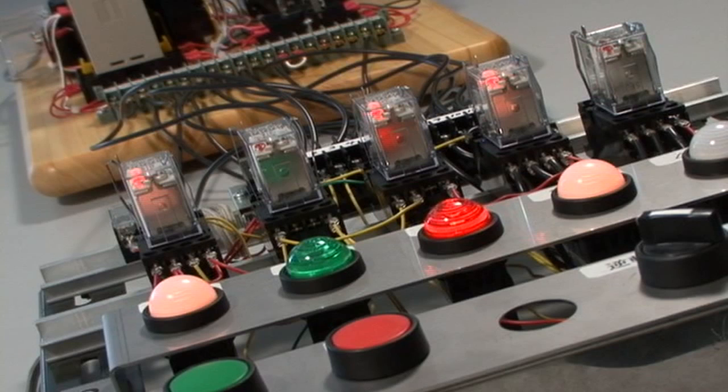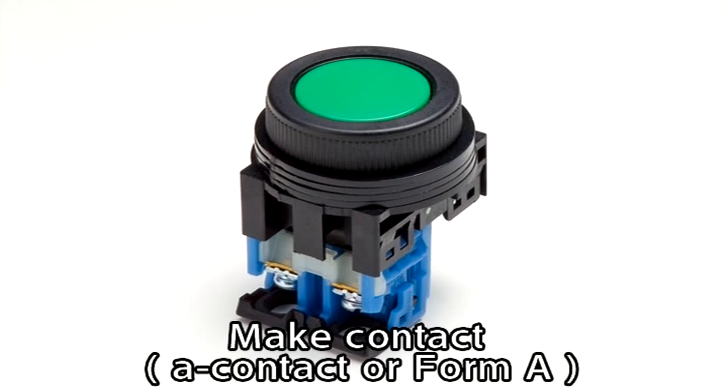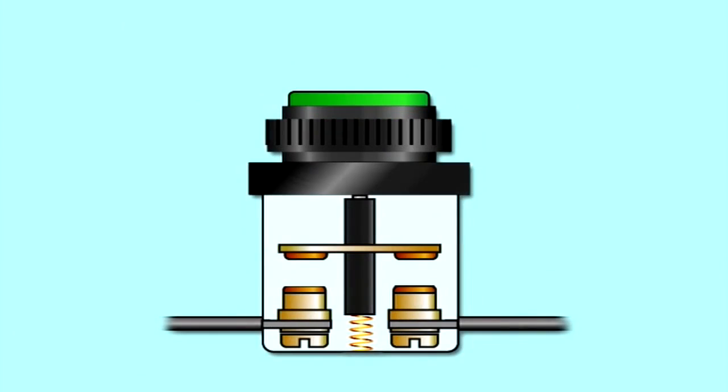Switches and relays are classified according to operation. The three types of operation are make contact, break contact, and changeover contact. Make contact is also known as Arbeit contact, which is abbreviated as A contact or Form A. If A contact is not in operation, the circuit remains open and the off state is maintained.